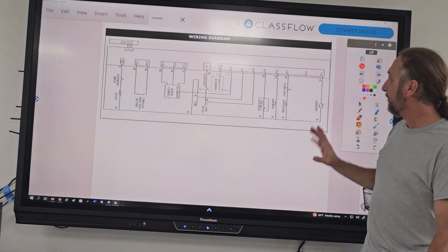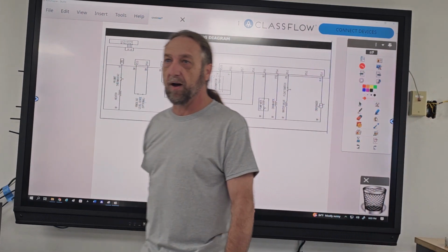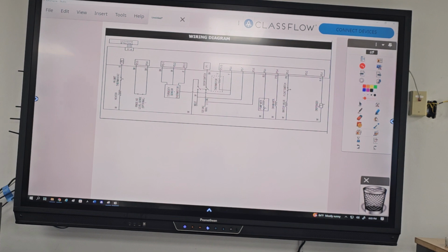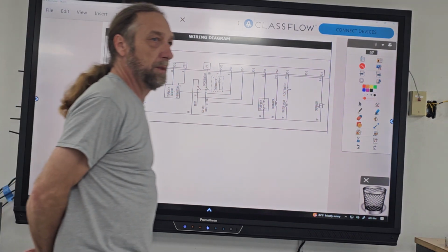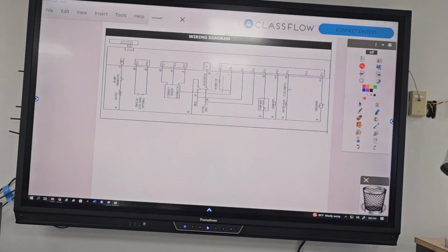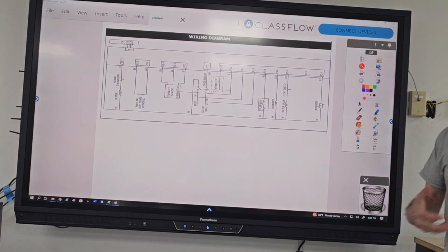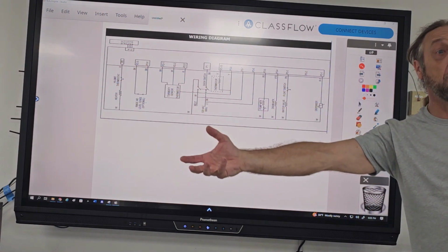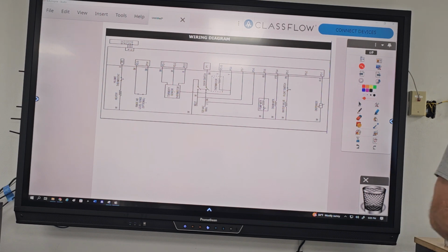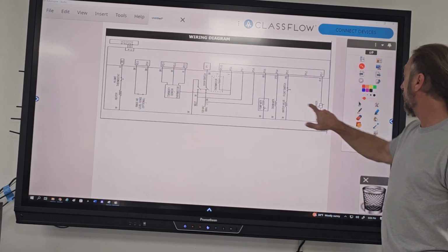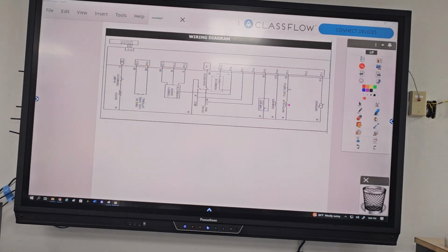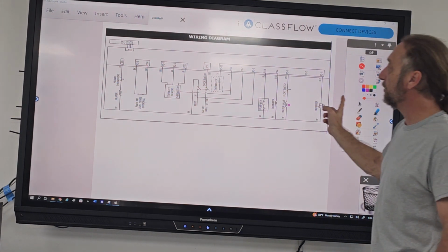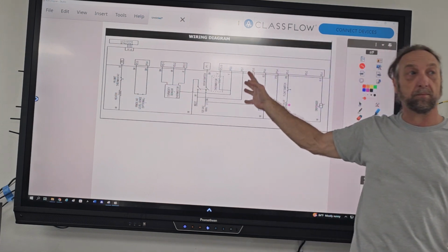So first let's look at this diagram here, take a minute, and try to figure out the loads that are in that wiring diagram. They are the things that we want the dishwasher to turn on so it does something. Like the water valve is a load because that lets water into the machine. So first of all, how many loads are in this entire diagram? Let's see.